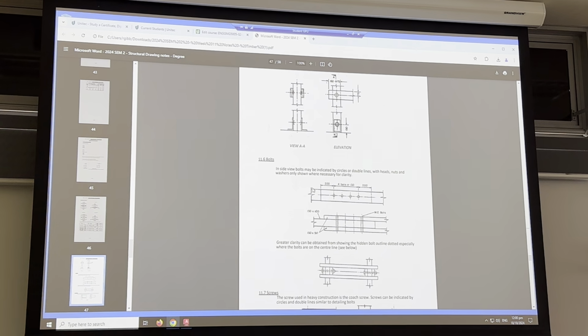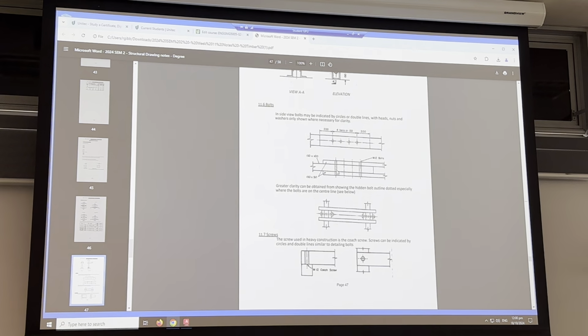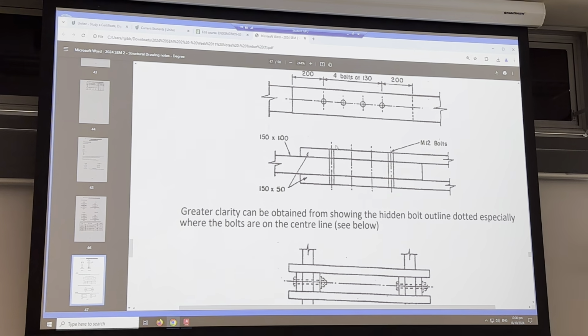We also talk a little bit about bolts, and any bolts in timber is called up that way with a distance and how many bolts there are. We don't actually do the individual little dimensions on timber. There's what I was talking about with the detail. You have the hole and a centre line showing that there's a bolt.